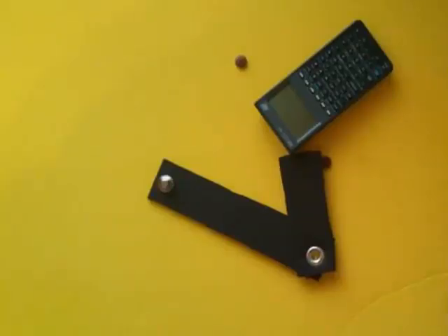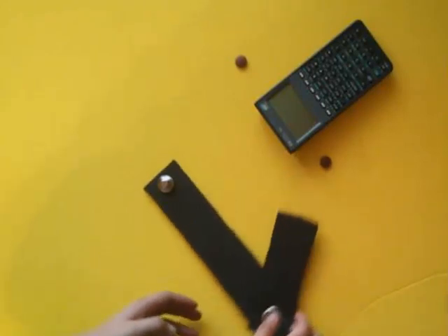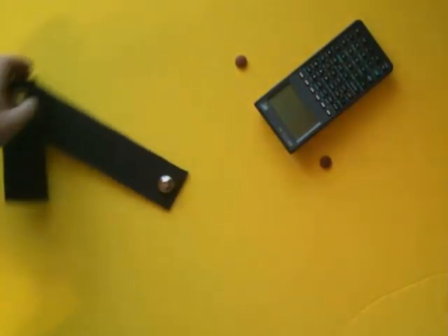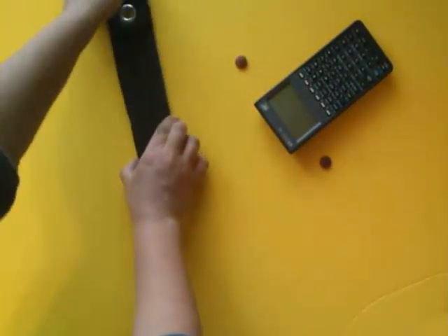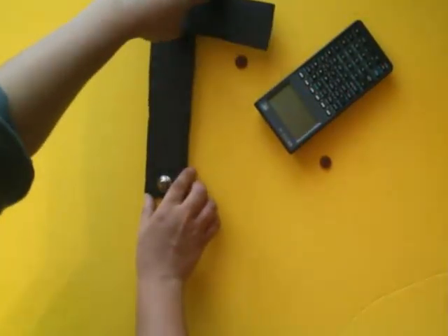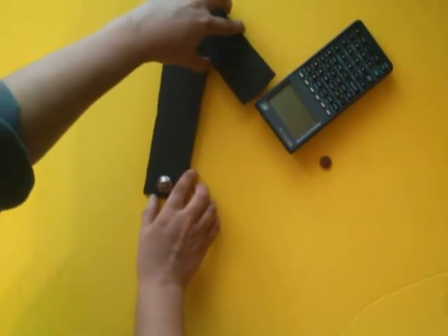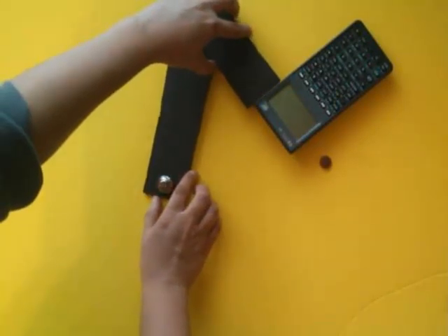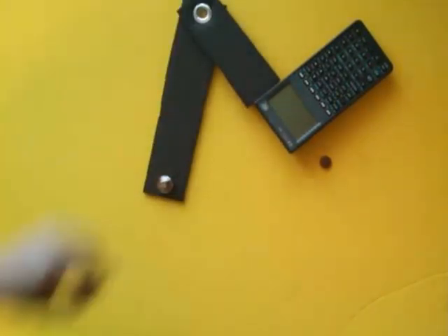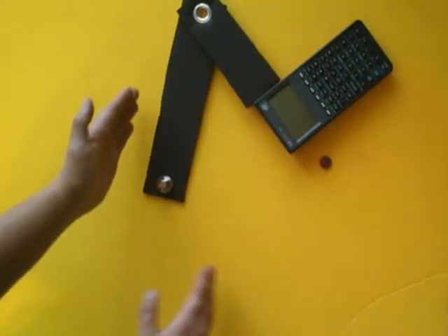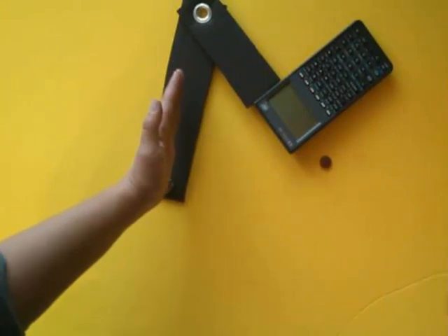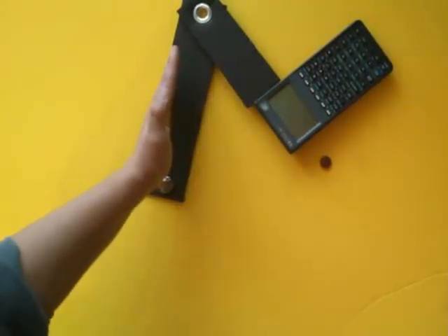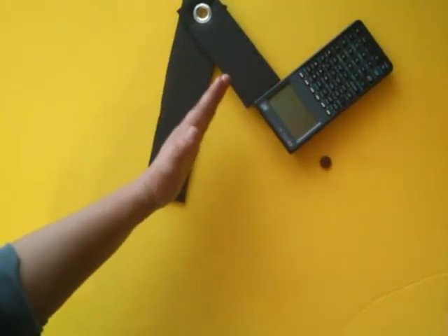I need to do the same thing on the other side as well. I'm going to move this manipulator around and find out at what angle the second link first makes contact with the obstacle on the other side. This angle is approximately 80 degrees, and the danger zone is less than 80 degrees.